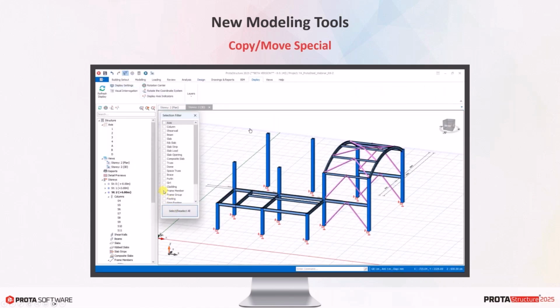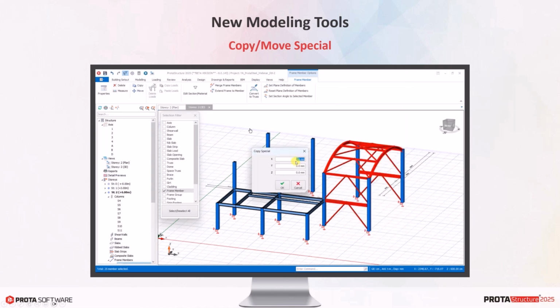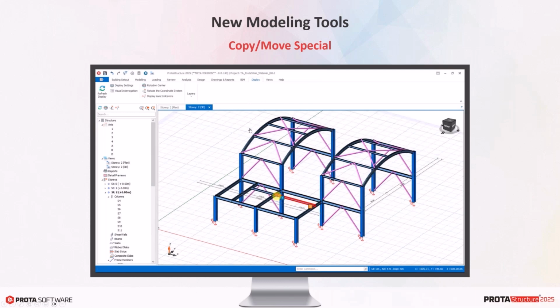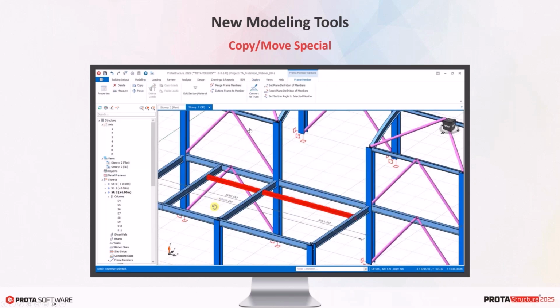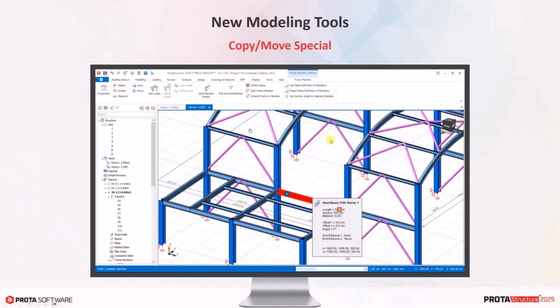Okay, and also in this version, we developed the copy special functionality, so you can select a bunch of members and copy special. In this command, you only need to enter the amount of distance you want to copy and the number of instances, and it will be easily copied. So again, maybe you want to copy them in the y direction, minus 2.5 meters, and that's done. And you can use these copy and move special commands very easily.